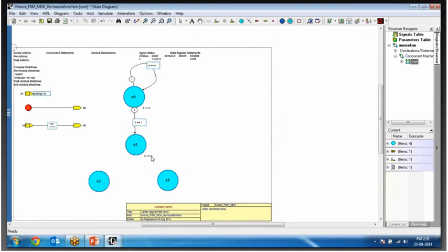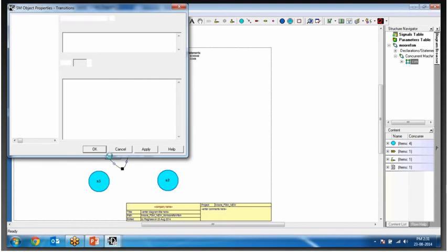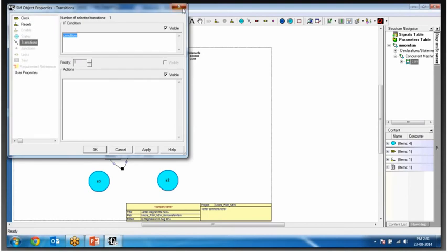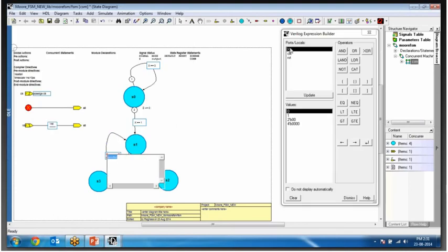So now z is equal to 0 is assigned to z again, because we have not found the complete pattern. So next I want a transition within the same state, to find if any more ones are there or not in the pattern. So I'll select this. I'll give a condition of if x is equal to 1. So if x is equal to 1, remain in the same state.